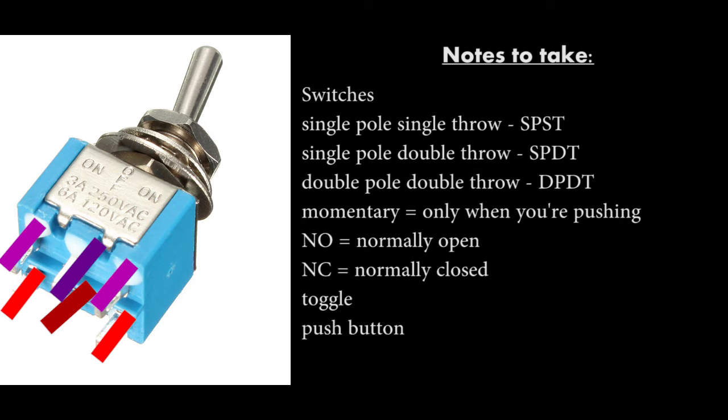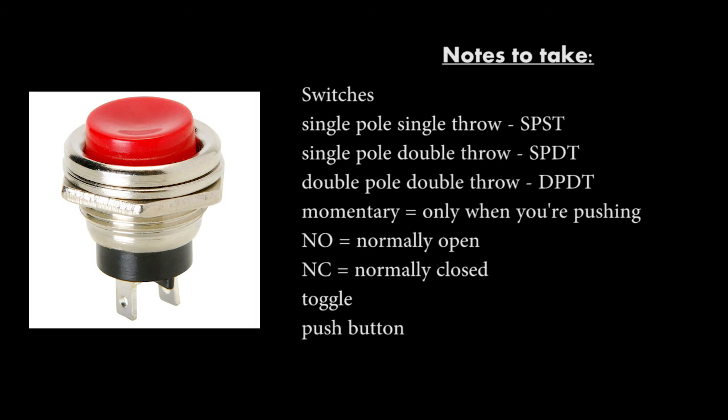DPDT. So here's a push-button switch. Now I don't know this for sure by just looking at the picture, but I'm going to go ahead and say that this is a momentary push-button switch. Momentary means that the switch is activated when you push it, and then when you let go of it, it switches back. Okay? That's momentary. It wouldn't be momentary if I push the switch and it actually latches down, and then I have to push it a second time to latch it back. That would be more like a toggle switch. Okay, so let's say that this is a momentary switch.